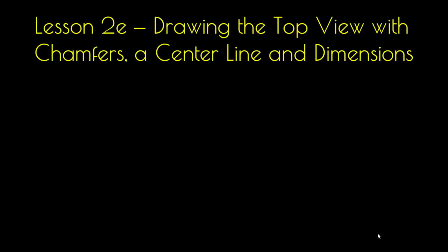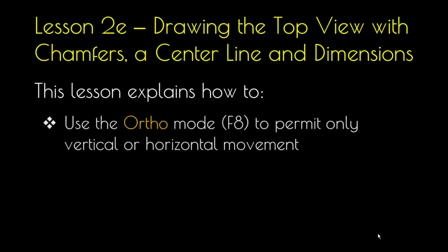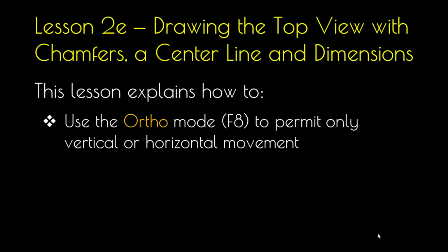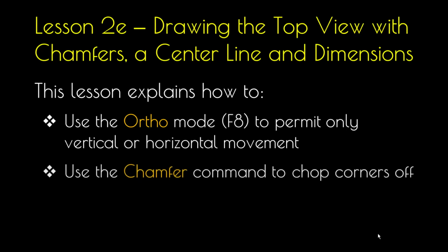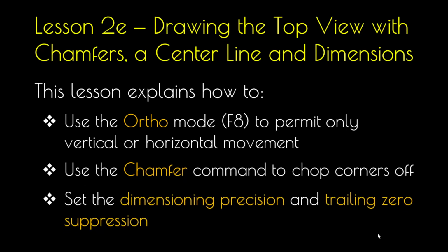Lesson 2E. Draw the top view with chamfers, a centerline, and dimensions. This lesson explains how to use the Ortho Mode to permit only vertical or horizontal movement. Use the Chamfer command to chop corners off. Set the dimensioning precision and trailing zero suppression.